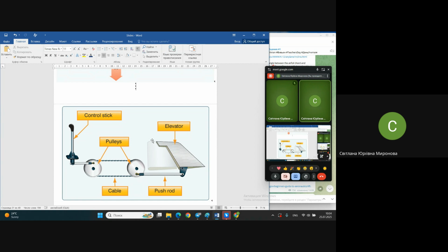Control stick front, or steering wheel pushed forward, is pitch down, nose down. Control stick to yourself, backward, or if we pull the wheel to ourselves, it's pitch up, nose up, and tail down. And right, left, quite clear, and pedals also. It's understandable for us. We may imagine the whole system.